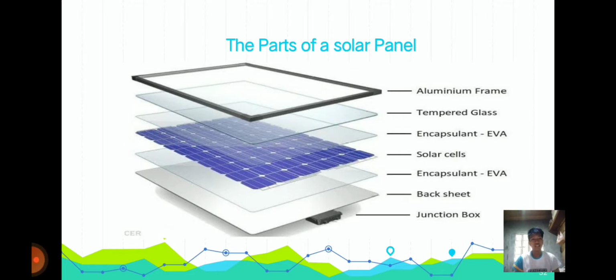And the glass, or tempered glass. The front glass sheet protects the PV cells from the weather and impact from hail or airborne debris. The glass is typically high-strength tempered glass, which is 3.0 to 4.0 mm thick, and is designed to resist mechanical loads and extreme temperature change.